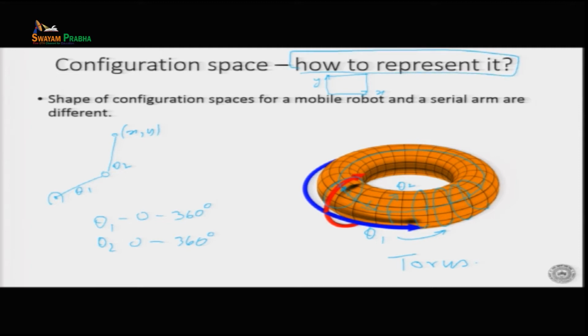When we looked at a mobile robot, let me draw that again. It was a circular mobile robot, and there was an obstacle, for example. I convert this into my C space. The mobile robot becomes a point, and the obstacle becomes a C space obstacle. Let us call it the C obstacle, and this has become my point robot. Now I could represent it in xy, which means it is still in 2D for a mobile robot.